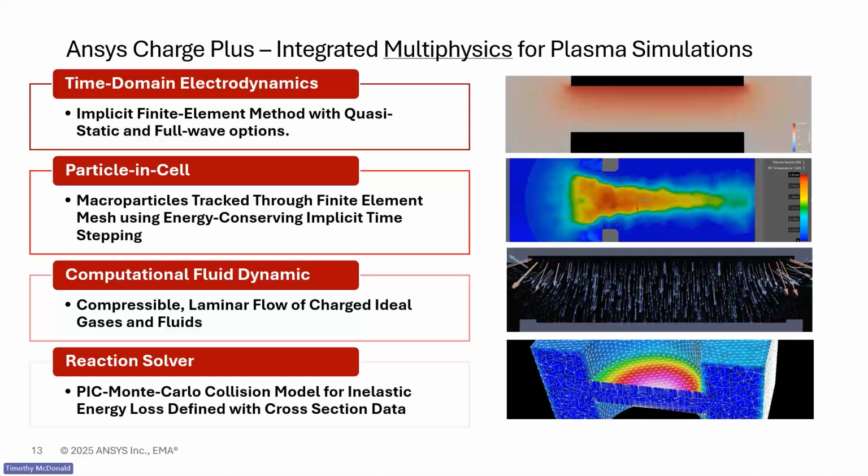Imagine literally particles that move in 3D on a 3D grid, where each particle is an ion or an electron. They're called macroparticles. Each macroparticle represents many, many electrons or many, many ions. By tracking them and their path in 3D, you can track the forces that are imparted on them and then feed back to the overall FEM or to the other fluid solver,